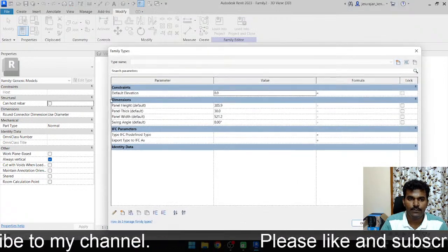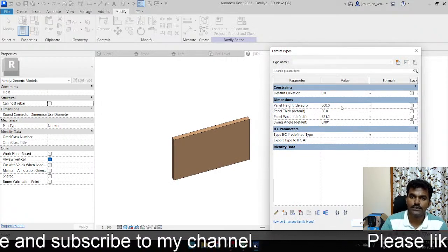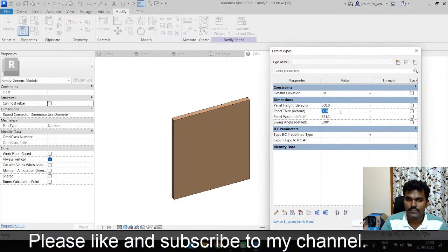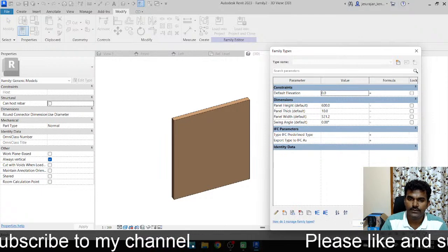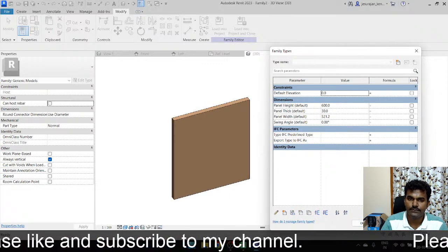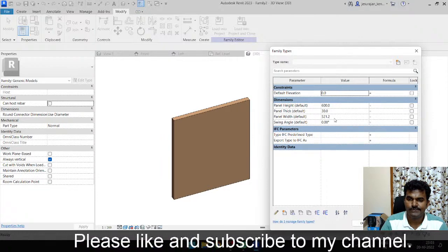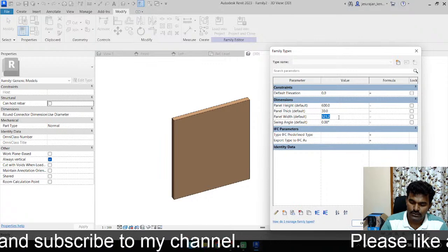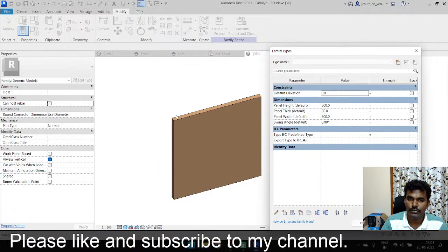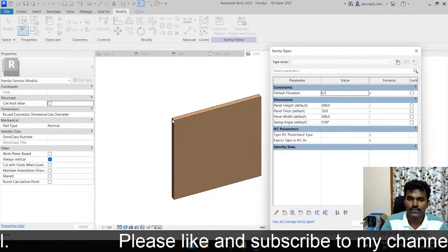Now I'm going to check my parameter. Panel height, if I'm changing it to 600, and if I apply, is it changing? Yes, it is changing. And the thickness, if I'm changing it to 10 mm, and if I apply, yes, it is changing. I can see it. Let's change it back to 30. Apply. It's changing. Panel width. If I keep it as 600, and if I apply, yeah, it's changing. You can see which side it is moving. So this is moving in the right side. That's correct. So left side we are going to keep it as fixed.